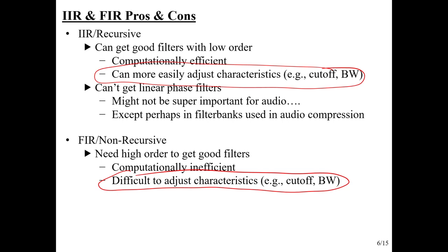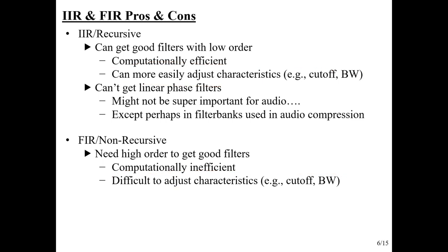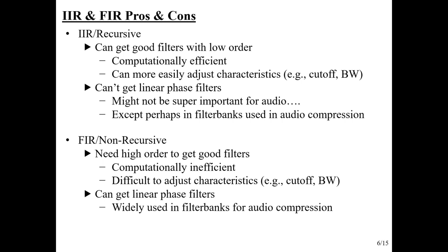You pretty much have to adjust all of the filter coefficients in order to get that to happen. But the big thing that FIR filters are good for is that we can get linear phase filters. And so that is a scenario that is, like I said, very useful in filter banks used in audio compression. It's also super important in some other areas that we're not interested in.